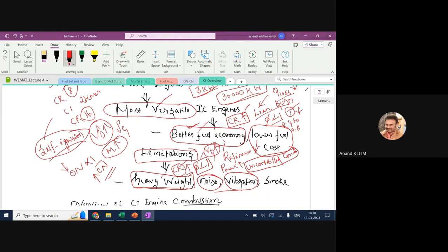The way the combustion even gets started in a CI engine is in an uncontrolled mode, and then it gets into a controlled mode. So there is some phase of uncontrolled combustion experienced by a diesel engine, which is not the case in an SI engine. That's why you have a poor NVH characteristic. NVH, noise, vibration, and harshness, is always poor in a CI engine because the combustion is a self-ignition or auto-ignition based combustion event.